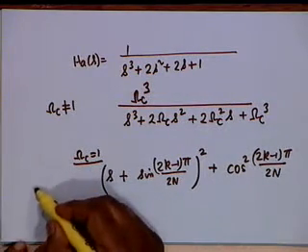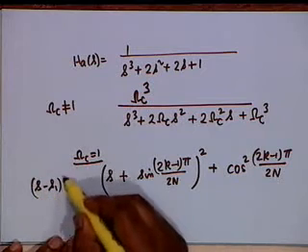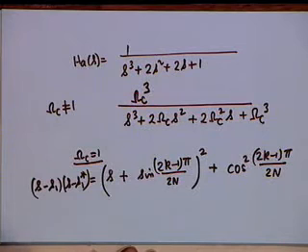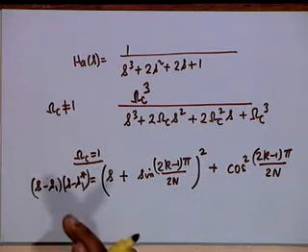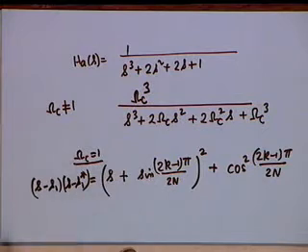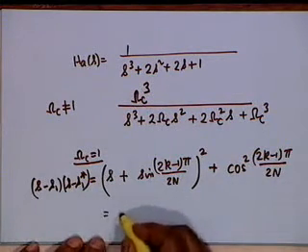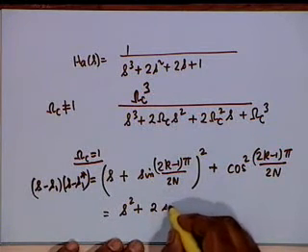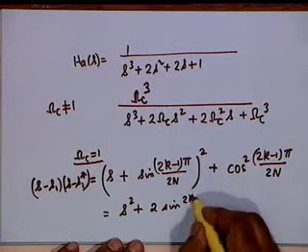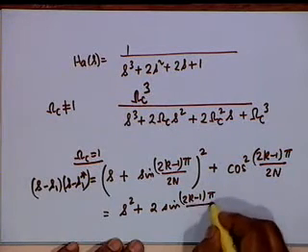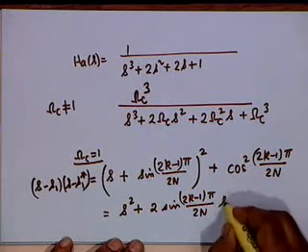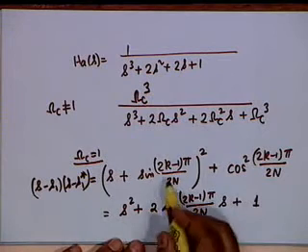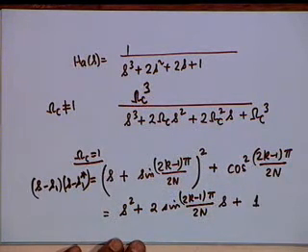All right, S minus a complex pole S1, S minus S1 star would be this. The product of two complex conjugate pole factors shall be like this, and this, as you can see, is S squared plus twice sine of 2k minus 1 pi divided by 2n times S plus 1. Agreed? Cosine squared plus sine squared is equal to 1.